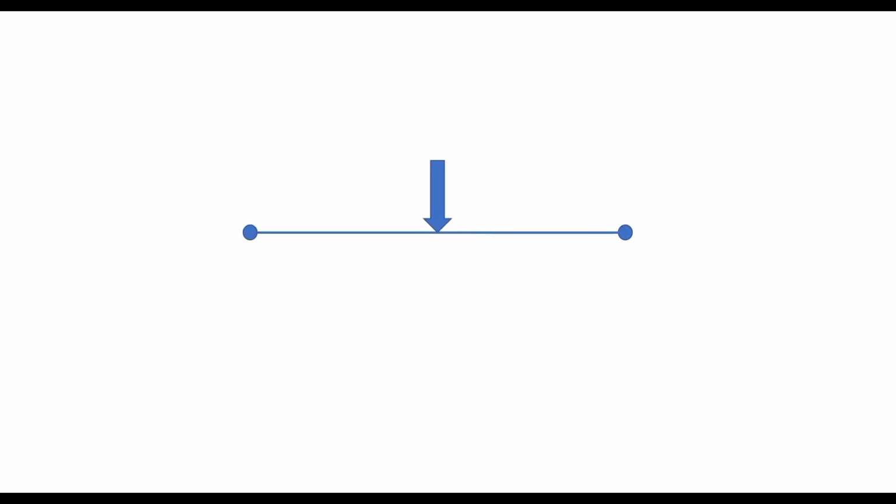So this would mean that under the vertical load, the system is in a state of unstable equilibrium. Again, we would need an additional horizontal reaction to stabilize the beam against a general system of coplanar forces.